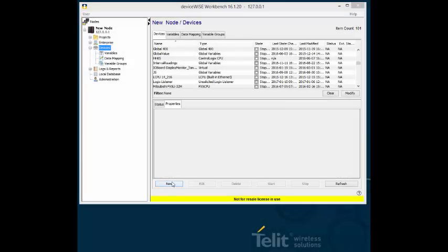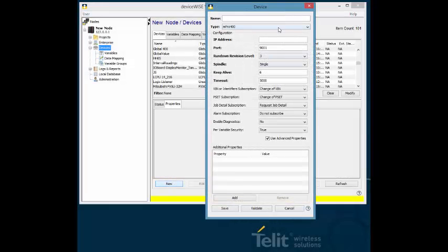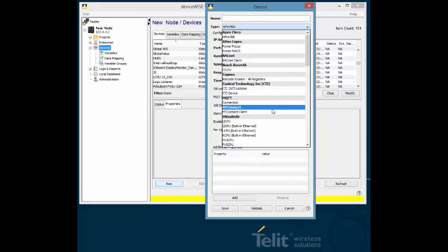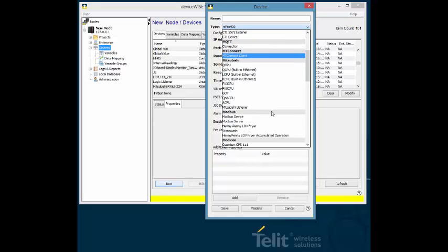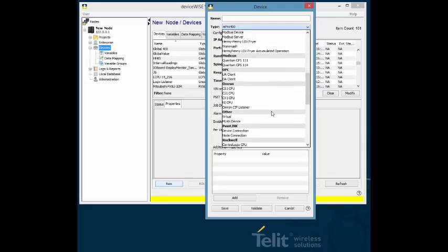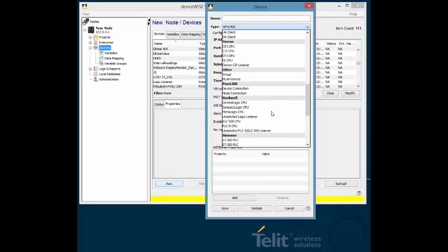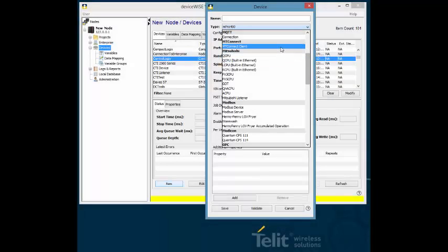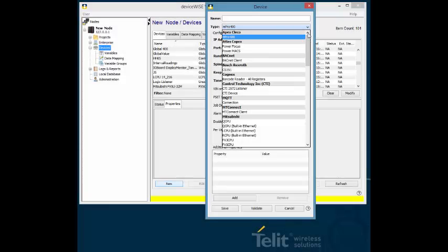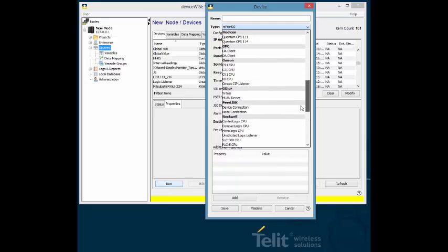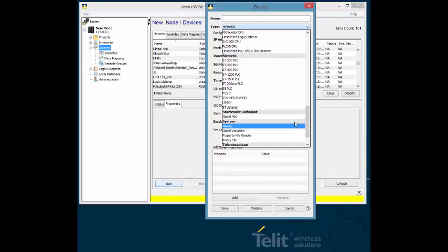deviceWISE contains a rich library of device drivers that provides connectivity to the most common PLC types. Drivers are written using the vendor-specific protocols for PLCs from Rockwell, Siemens, Mitsubishi, Omron, and Beckhoff. Drivers are also written that speak widely used protocols such as Modbus, MT-Connect, OPC-DA, and OPC-UA. One of the more commonly used drivers speaks the open protocol implemented by DC tightening tool vendors such as Atlas Copco, Apex Cleco, Bosch, Stanley, and Sturtevant Richmond.